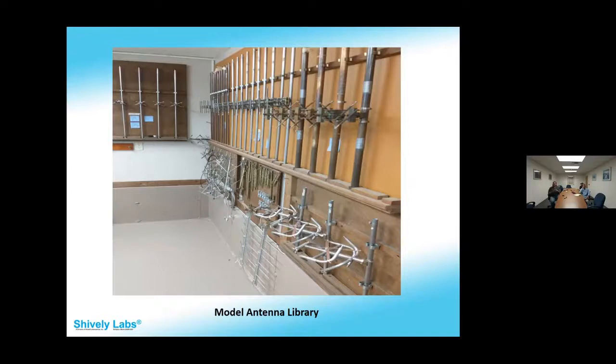And what we found works very well is blocking that at the receive antenna with absorber material, or changing the beam width of the receive antenna. Those are two techniques that we use to keep that contamination from happening. And that's another limitation of our range, is we do single element azimuth patterns.